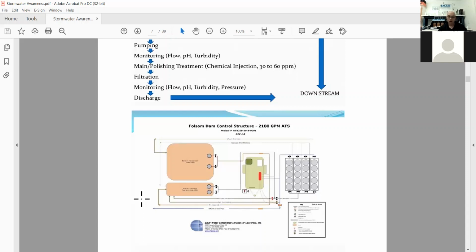So effluent monitoring requirements change with dewatering systems. Typically, the dewatering system will be run in recirculation, then sampled to see that discharge requirements are met. After verification, the system will then be monitored on a periodic schedule developed for that discharge location. And that's provided you're not using chemicals. If you're using chemicals to remove that fine suspended sediment, you will be doing daily residual tests. But if you're just running a dewatering system through a media, once you've guaranteed it's working, then it only has to be checked on a periodic basis.